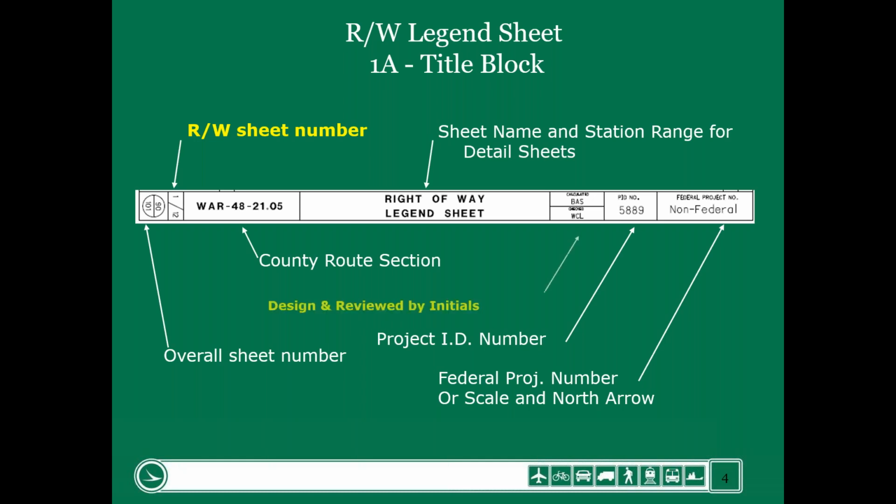The other thing we do in right-of-way plans is this: there are 2 people that are required to be pre-qualified. Actually, the firm is pre-qualified, but the design firm must have 2 individuals, one being a designer and one being a reviewer. The reviewer must be a licensed surveyor.